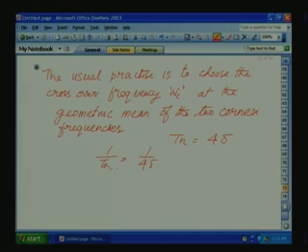then let us substitute this in the loop gain and find out what phase margin we are getting. Based on this, at the gain crossover frequency where the gain will be 1, let us find out what is Kn, and with that Kn let us find out what phase margin we are getting.